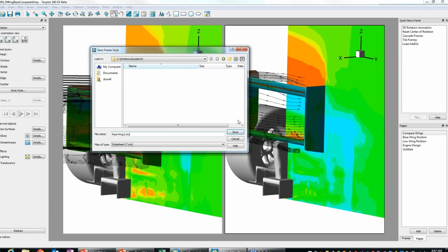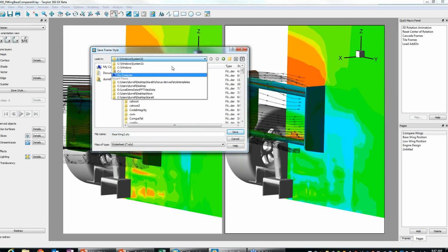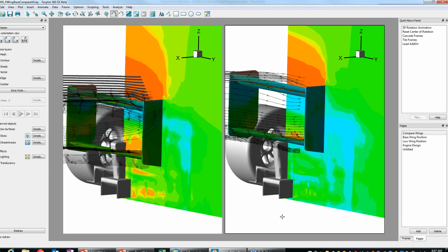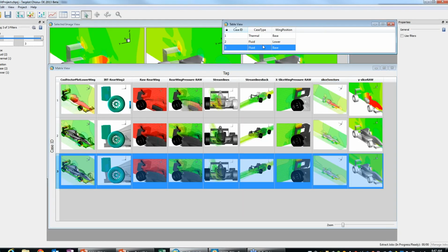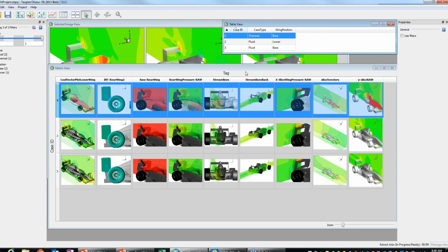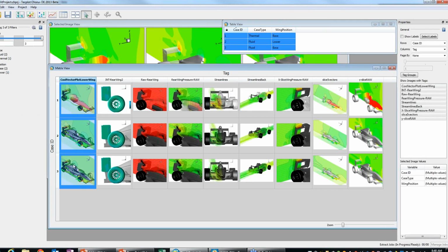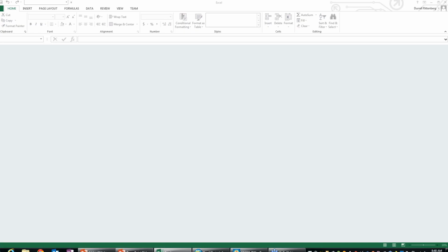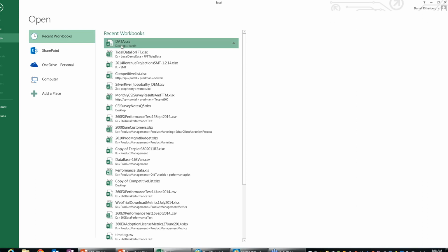But as you know, we're looking at three cases, and although I could set most of this up in batch, if I want to evaluate each of the three models in context, I can use a tool called Tecplot Chorus. And so I want to show you quickly how that works. So these are the three cases, and basically we have the two cases which are purely looking at rear wing position. And we also have the case which is the thermodynamics with the engine, which is radiating heat at 500 Kelvin. And you can see that I have the three cases, and how I generated those cases was actually very simple. And I'll open up the file so you can see it.